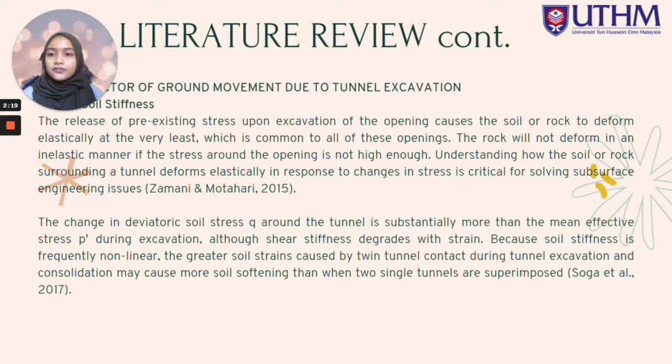So the next factor is soil stiffness. Zamani and Motahari state that the release of pre-existing stress upon excavation of the opening causes the soil or the rock to deform elastically at the very least, which is common to all openings. The rock will not deform in an elastic manner if the stress around the opening is not high. Understanding how the soil or rock surrounding a tunnel deforms elastically in response to change in stress is critical for solving subsurface engineering issues.